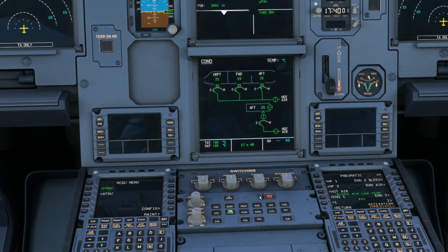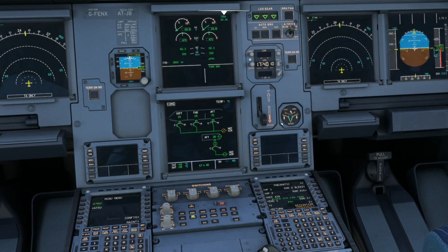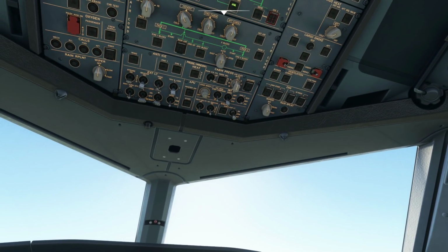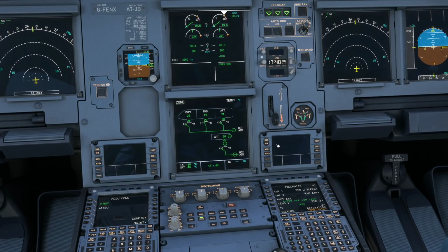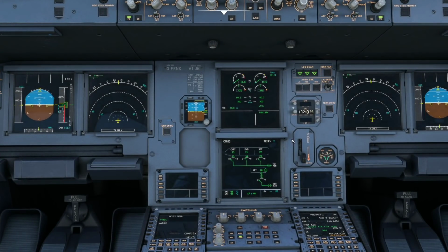Okay, so now we've seen the packs regulating temperature on their own. We'll just set it back to the way it should be, which is letting it do its trimming. So there you go. It'll start trimming according to what you've requested, and we'll just set these back to relatively sane temperatures. There you go. And we'll watch it start trimming its way up. Those relatively sane temperatures should be around, looking at that, 24, 18, so it'll be somewhere in between. And once it gets to where it needs to be, it should level itself out again.